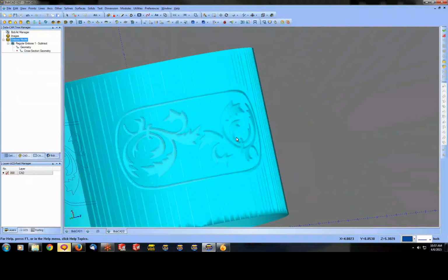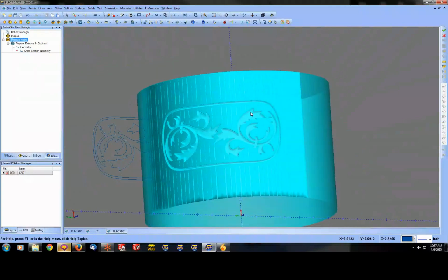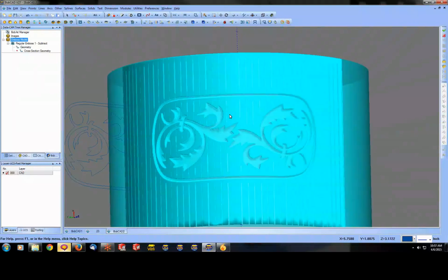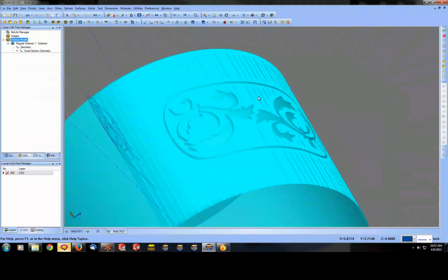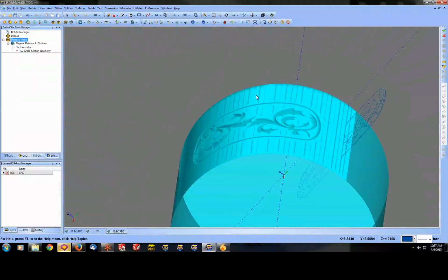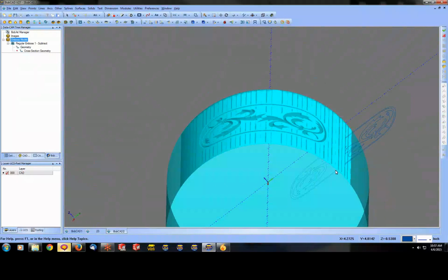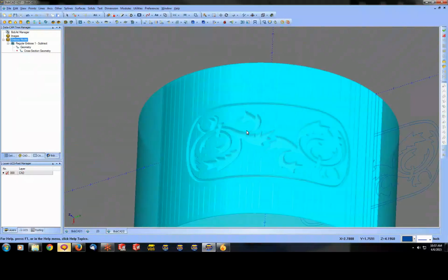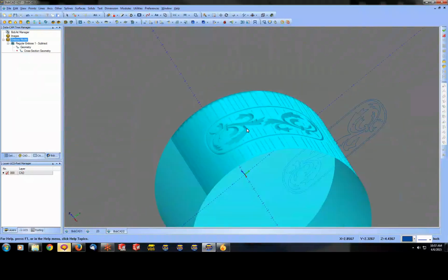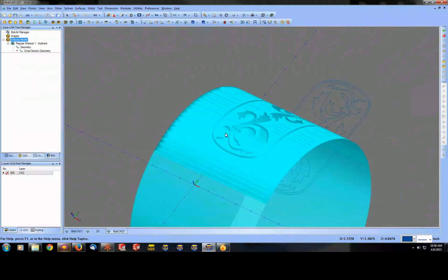Now, really, you would probably use a wrapping group for something like this. This is simpler as far as getting it on a cylinder, but as far as machining it out, this will probably give you more issues. You could create a plane to index to machine it that way, but without simultaneous movement, you won't get it right.